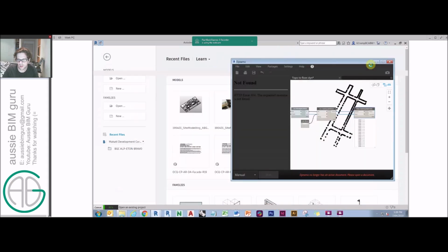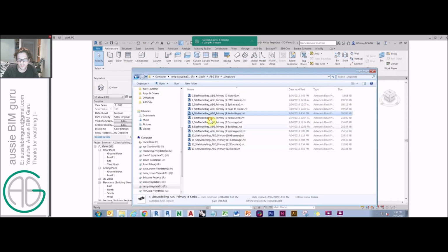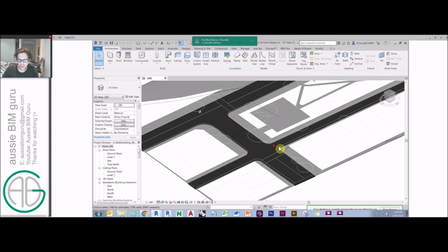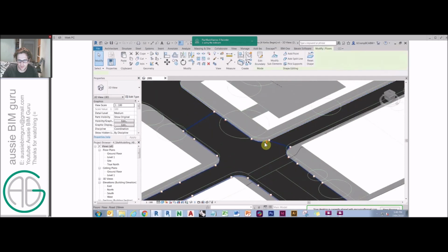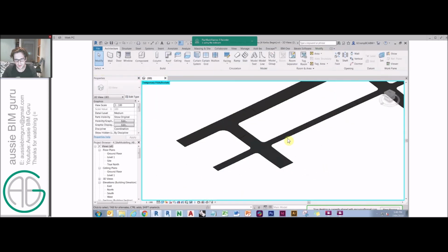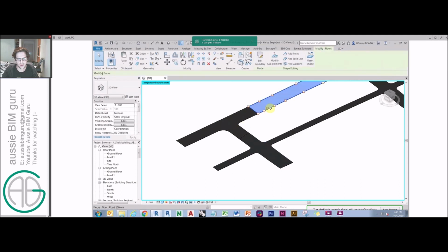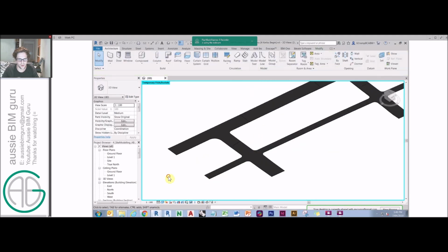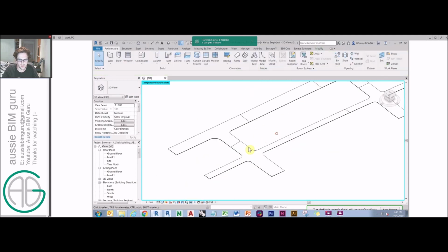before I begin my curb modeling, just close Dynamo. So you'll see at the moment, I've actually cleaned up everything quite a lot. You can see I've broken the floor into multiple pieces. So I've divided it. I've applied a road material to it as well, just for later. But at this point, really what we want to do is actually model the curbs. So I'll just go to hidden line mode to make it a bit faster.